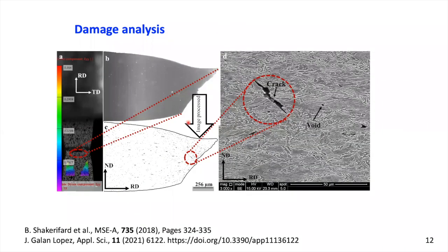We even developed this one step further by looking very much in detail at damage initiation, in fact. So if you have fracture, it's the result of a process, and this process starts with small void nucleation, and we made so-called void maps on tensile test samples. This was for a dual phase steel.